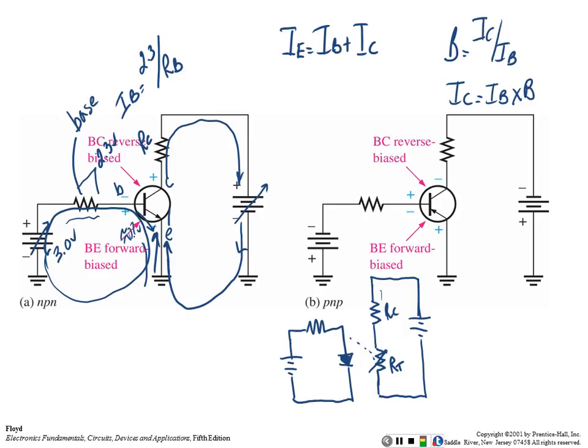So that means if I look at a transistor and it's got a number on it, beta is going to be within a range, right? You understand? Another thing is beta varies with temperature, and we'll look at this. We'll hook a heat gun up to this thing and watch the transistor saturate, because we don't have any temperature control. Normally when we design circuits, we try to prevent thermal runaway, and we'll look at that as we go along.